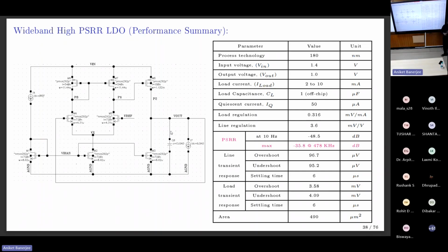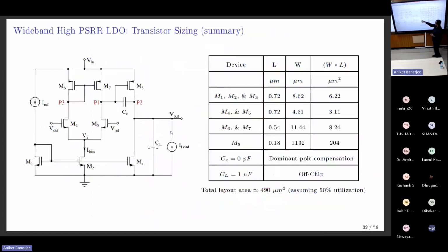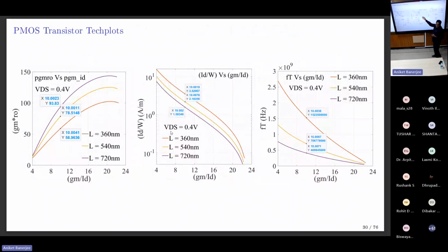Again, you have to sit with the transistor to do well in this, and you have to sit with the topology to do well in this. So understand all the circuits, then tie it back to the lookup table methodology, like how you tie it to the square law methodology. If you had used square law, this table would take time to come. Now it is there in the first iteration. And if you had generated the lookup tables with even finer resolution points, you would have been right on top of what you want.